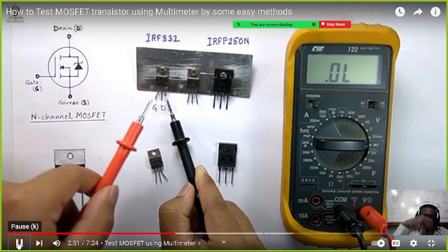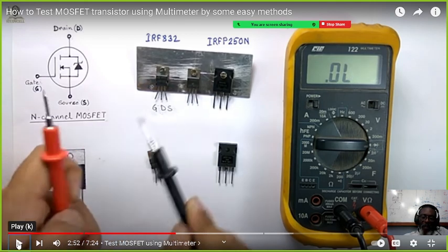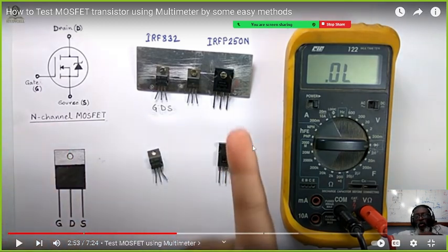Let me tell you, when I put it on the day of testing, the meter also puts a DC voltage on the red lead. Remember, when you're using the tester, especially when you're testing resistance and diodes, it's really a voltage that comes out of the lead.